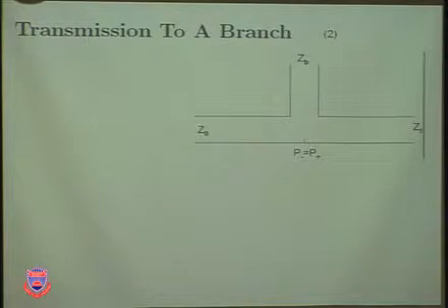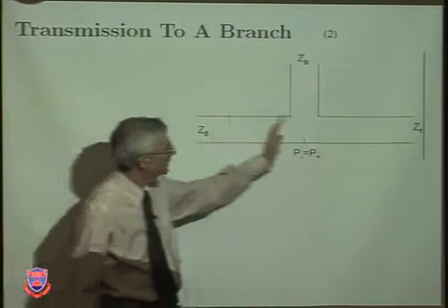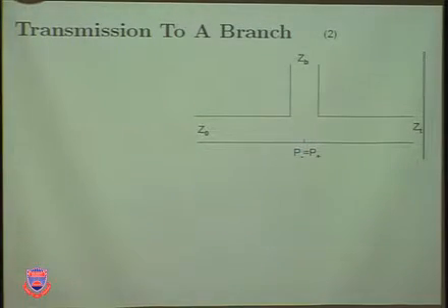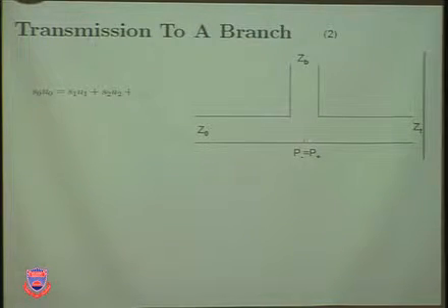When you have a branch like this, and these are very common, and you have sound pressure propagating, but then there's another duct that takes off. It's not so different from the previous one, but basically we have a relationship between the areas and the particle velocity to all different branches, but the pressures must be the same.